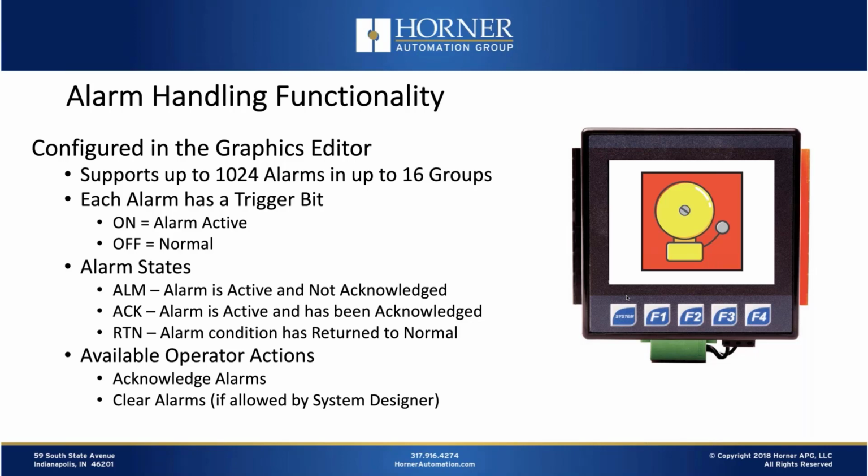And then when the alarm condition has returned to normal and is no longer active, we call that return to normal, RTN. And from the standpoint of the operator, there's at least a couple of actions they can take in reaction to alarm conditions. One is they can acknowledge them, typically by pressing the screen and pressing an acknowledge button that's affiliated with the alarm object. And in some cases, they can also clear alarms if the alarm is no longer active and if the system designer has provided a clear button or enabled the clear button that's also part of the alarm object.